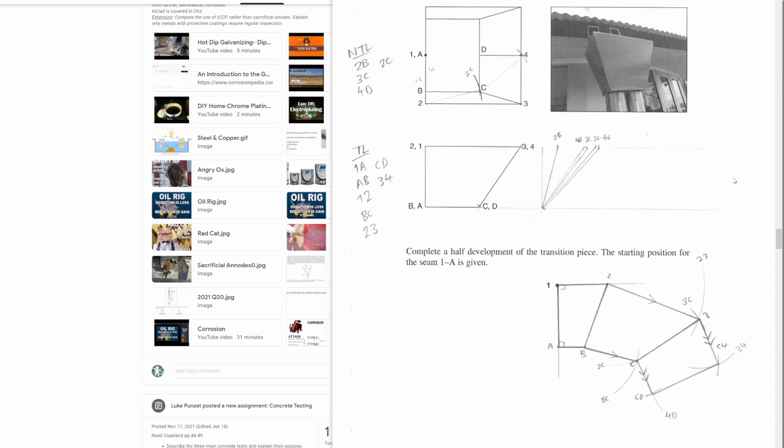Let's start here with 4D. 4D is this length here, and it's this length here. They can't both be right. They're clearly different distances. But because 4D is not moving away from the camera, point 4 and point D are both the same distance away from my eyeballs. That means in this view it's a true length. We can just measure straight off.